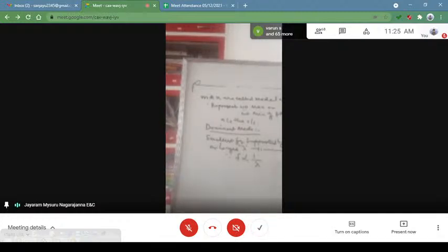And corresponding to the waveguide system, generally your waveguide will act as a high pass filter that we are going to prove later when we consider the waveguide parameters. Waveguide acting as a high pass filter means if you write the response, it will be in this ideal form. It has a cutoff frequency. That means the waveguide is to be operated above a certain frequency only. Below this, the waveguide cannot be operated.